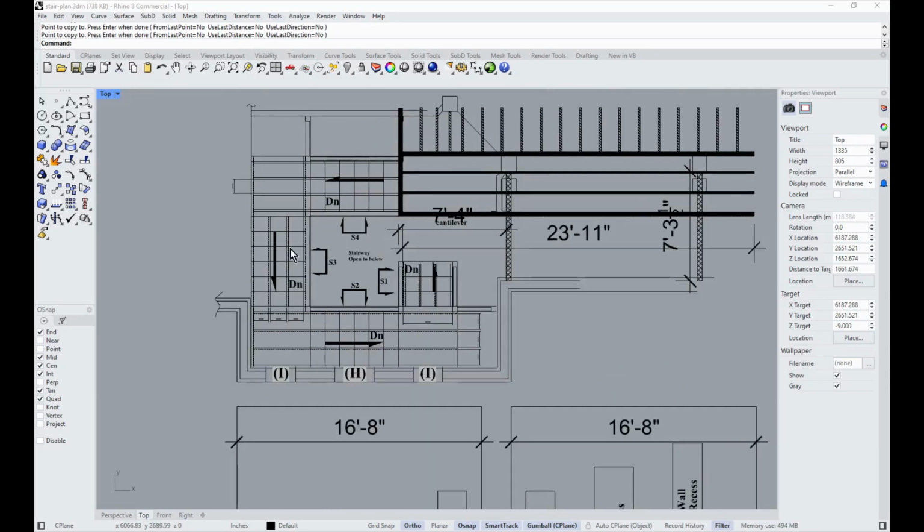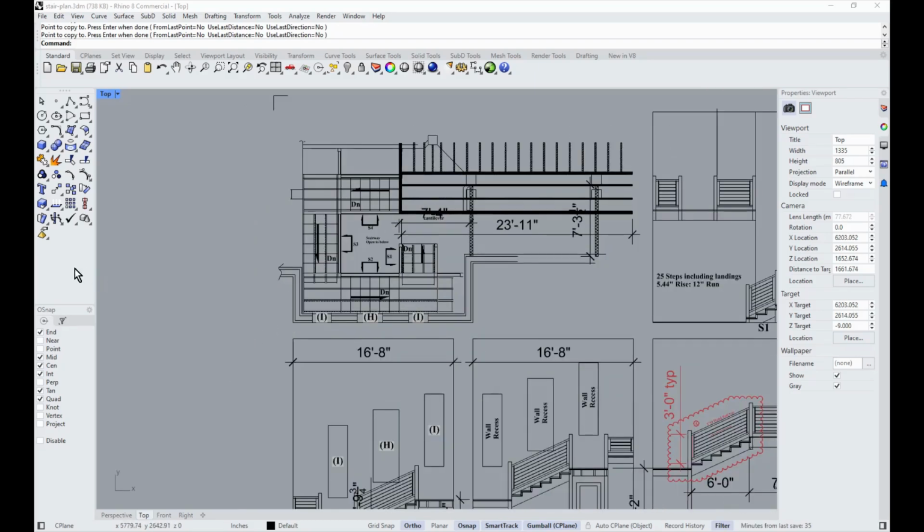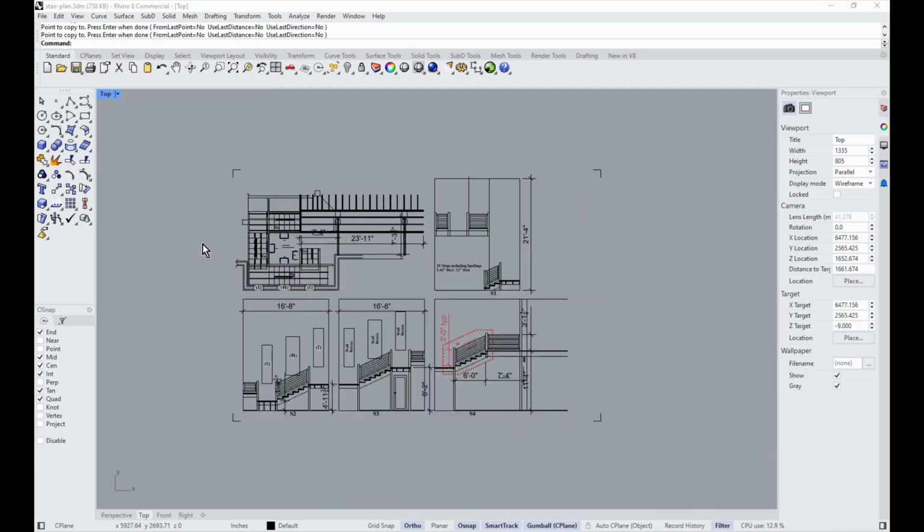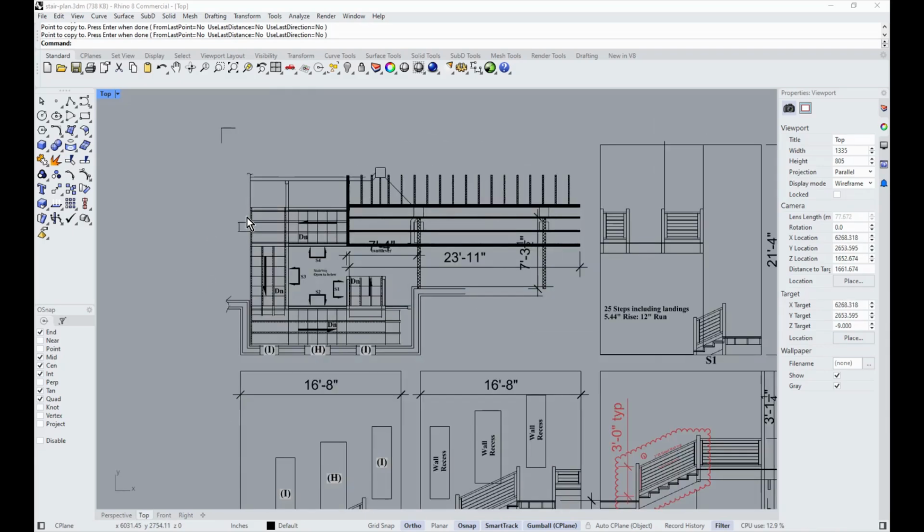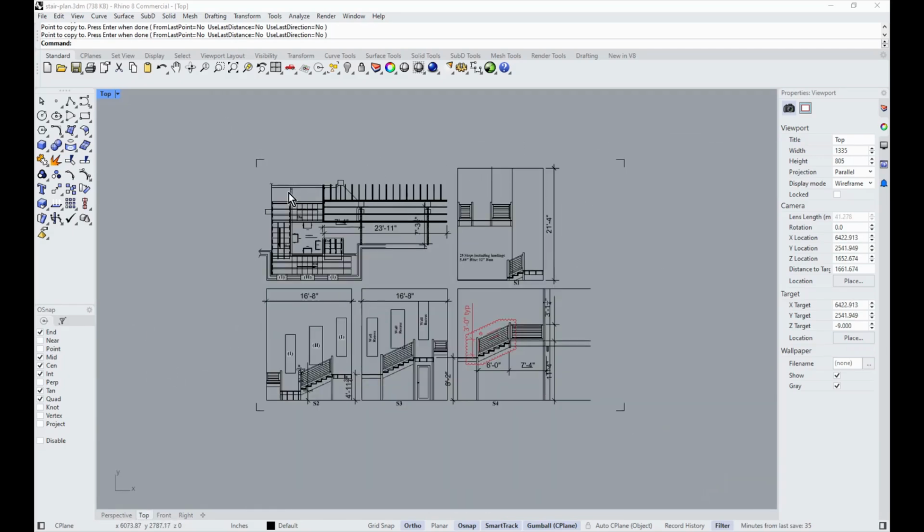So consider maybe some landings as well with your staircase design if you're limited with what you can lay out in your floor plan. Then you can use some landings. The house I grew up in had a cattle chute stair that was totally straight. But any more, these landings are going to fit into architecture and floor plans a lot easier. They don't need that really long set of space to make it happen.